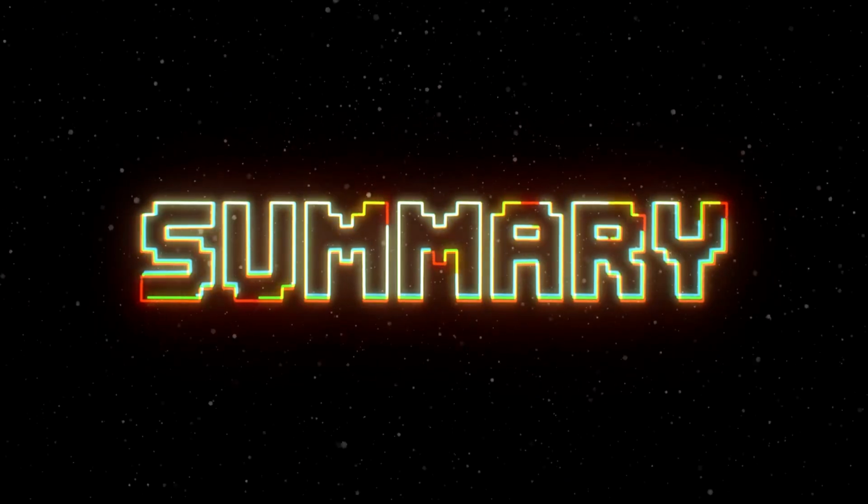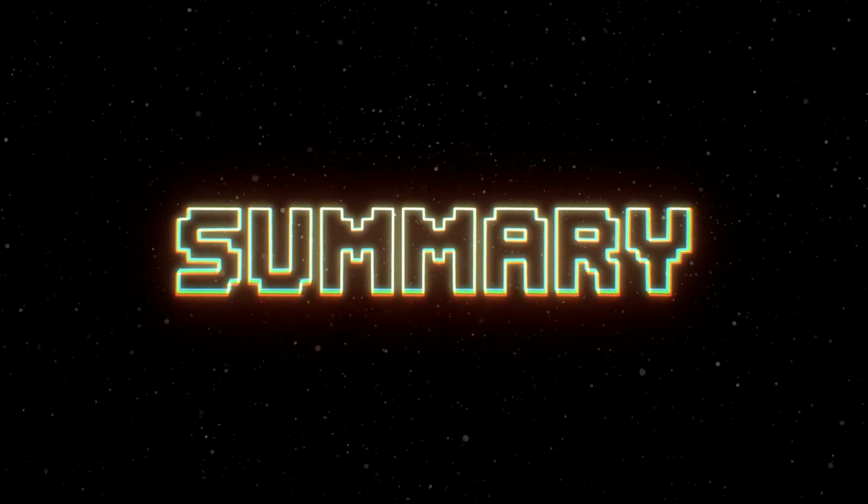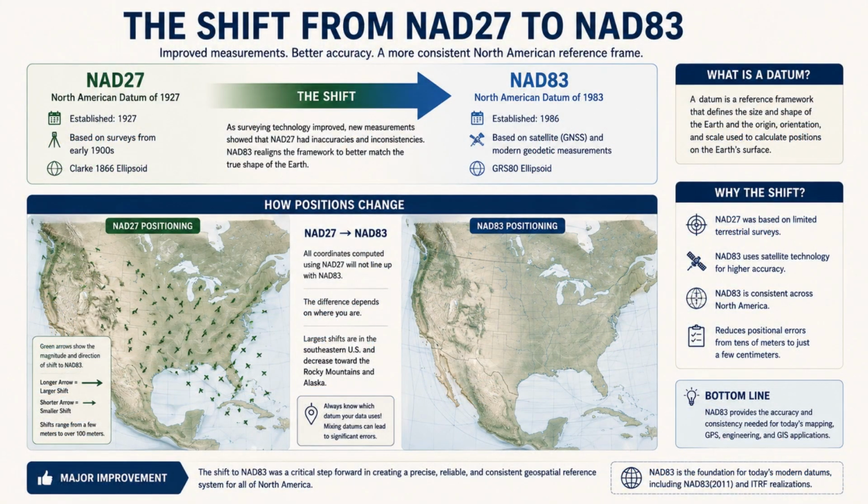Okay, let's run through a rapid-fire summary of your Section 103 study checklist. Let's do it. You need to know the difference between the physical, gravity-based geoid and the mathematical reference ellipsoid. Right. You have mastered the 4 types of heights, specifically recognizing geoidal separation as the mathematical gap between the ellipsoid and the equipotential surface. The gap between math and reality. Yes. You understand why surveying transitioned from the localized, optically triangulated NAD-27 to the geocentric, satellite-based NAD-83. Leaving the Kansas ranch behind.